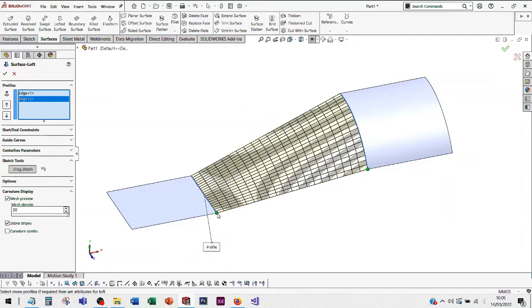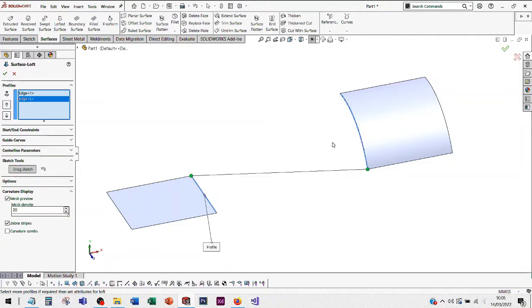If you see nothing at all, you probably have a twist condition, whereby Solidworks detected, as you were clicking along, that it should start from one point on one edge and end up on another point on the corresponding edge.